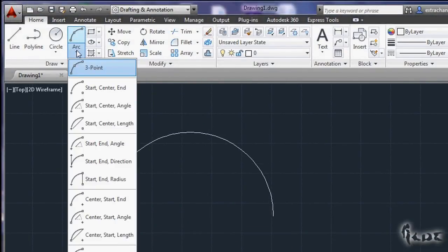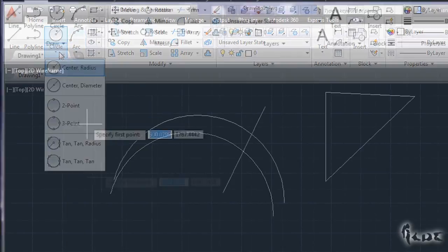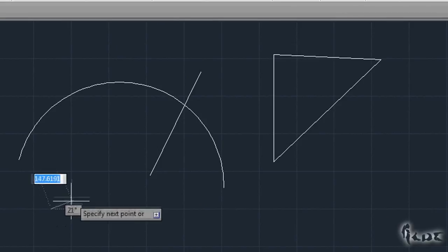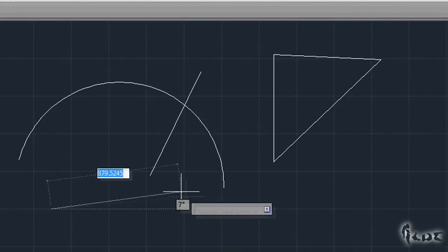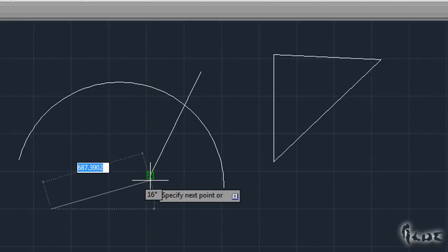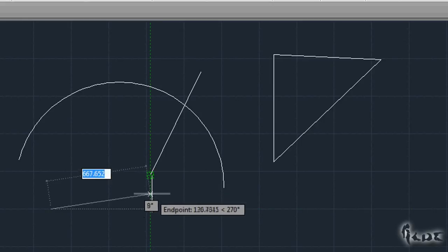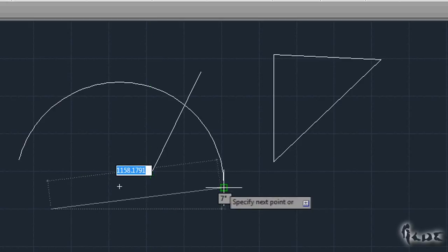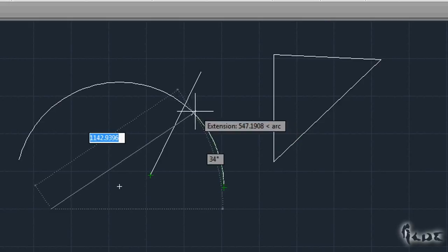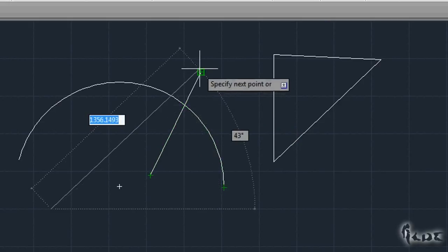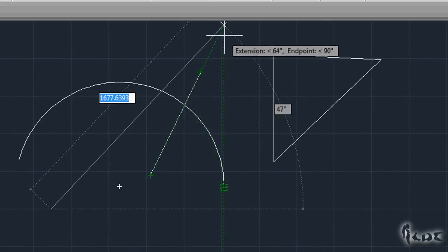You can choose the order to set points or distances or angles by clicking on the black arrows above and selecting the way of drawing, as explained before. These green squares or lines help you to draw precisely, through a precise axis or while connecting two different objects drawn. Squares often represent corners and endpoints of the drawings. The cross means intersection between objects, and the dashed line, the straight line intercepting an object's point.